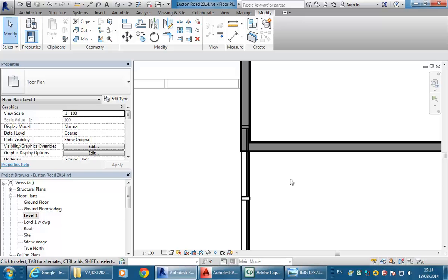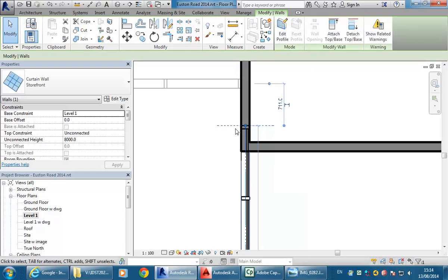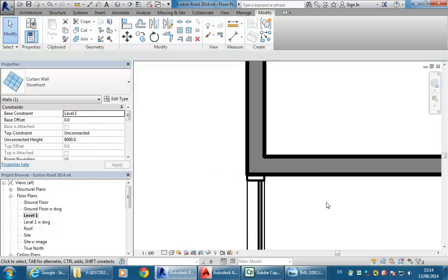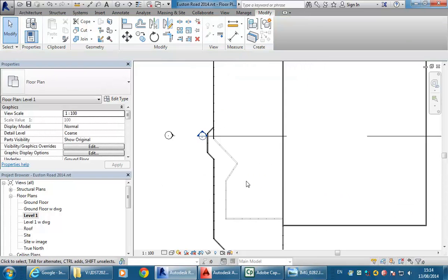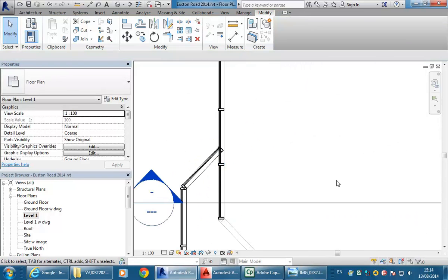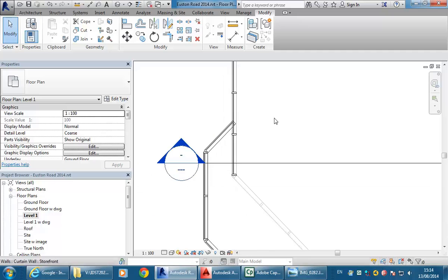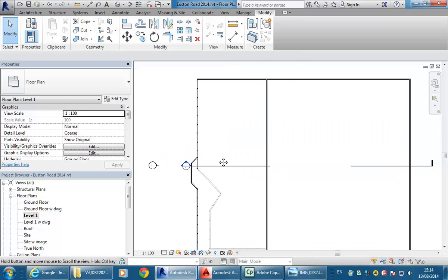Yeah, and that's a really good point. So you should do that. And it's easy in Revit. So I'll just get this curtain wall now and stretch that down to the bottom there, and then back to this part here. That's going to create a problem, obviously, on this floor, but we'll maybe worry about that later as long as you're aware of it. There are different approaches you can use to fix that.